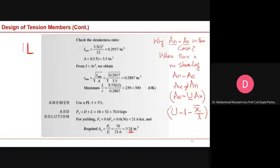Angle, and you have a double angle, a built-up section, and these two are connected with the help of a plate, a gusset plate. Or only this part is connected. This part is connected, this part is not connected. When one part is connected and the other part is not connected, the stresses will not be uniformly distributed.